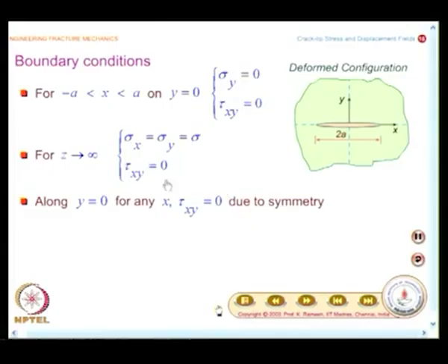So, that means along the crack axis there is variation of maximum shear stress, and here you are making a statement along the crack axis in-plane shear stress is 0. This is correct, but what we would show later is by imposing tau xy equal to 0 without our knowledge, we have also imposed maximum shear stress is 0 in the process of the solution development. This was not looked at by people in the initial stages. This was discussed by Sanford way back in 1980s.